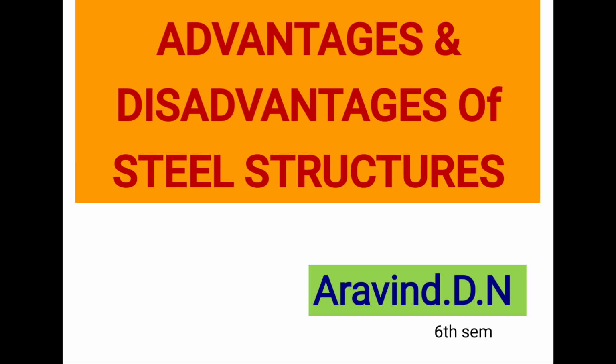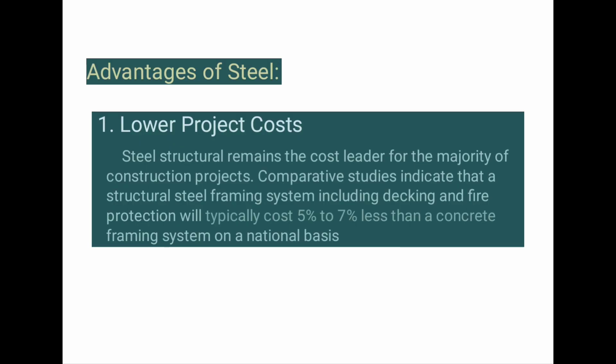Today, I am discussing the advantages and disadvantages of steel structures. First, we will discuss the advantages, the first one being lower project cost. Yes, steel structures remain the cost leader for the majority of construction projects. Comparative studies indicate that a structural steel forming system, including decking and fire protection, will typically cost 5% to 7% less than a concrete forming system on a national basis.